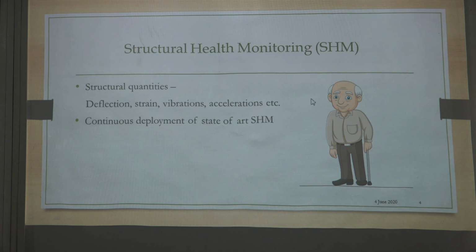At a young age the structure does not require any kind of assessment, but as it passes a certain lifespan, it requires frequent monitoring of some structural quantities like deflection, strains, vibration, acceleration. The loss of life is less by doing this particular exercise.